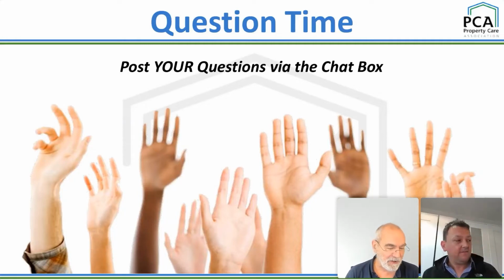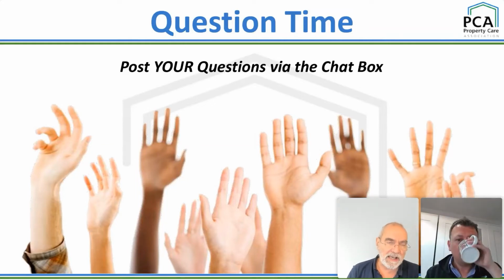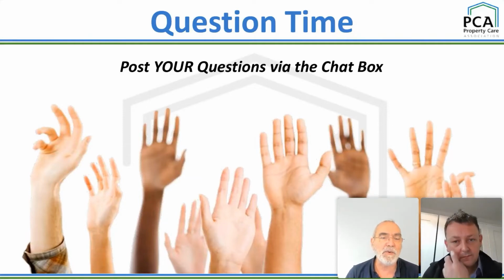Yeah, I've got a piece of string here. I think the actual process of testing, you saw in the brief video of the arc testing, effectively you're pushing a brush along the roof. Now, I think it's probably fairly easy to estimate how much you can cover in an hour. I would suggest you're walking between 2 and 3 kilometers per hour. Let's say 2 for easy numbers, and you're probably using a half-meter wide brush. So you're going to do about 1,000 square meters an hour. That would be relatively easy.